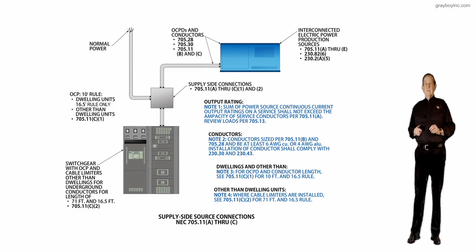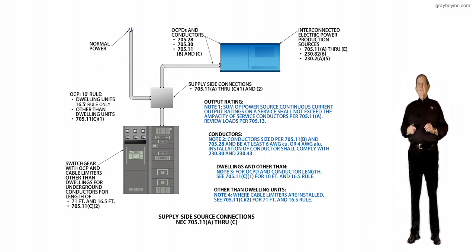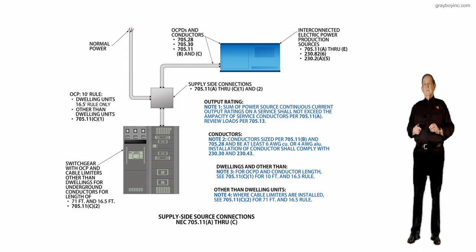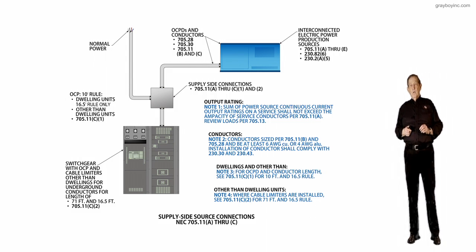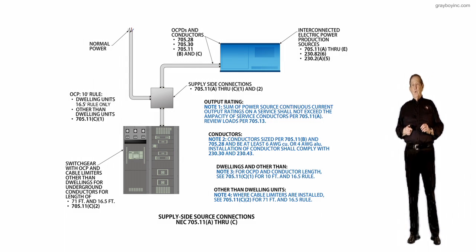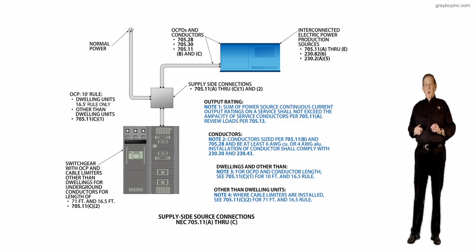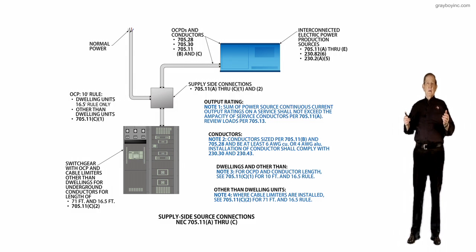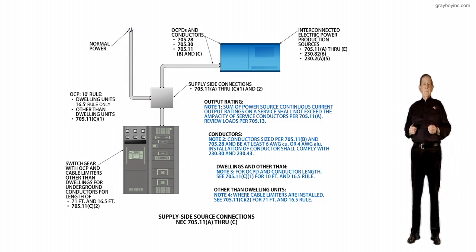Also, the note recommends that you review 705.13 for loads. And of course, you calculate loads by 230.42(A)(1).